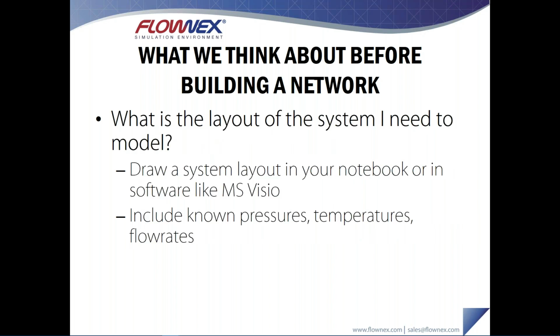The next thing that we need is some layout of the system. Often what will happen is engineers will be working in big plants, or somebody will describe a new system on a whiteboard, and we'll start building right away without actually considering the system in more detail. Taking 10 minutes or so and drawing out the system, be it in a notebook or even in something like Visio, you can gain a lot of insight into the system, make sure that you understand the layout of all the components, and more importantly, include information you already know about the system. Known pressures, known temperatures, known flow rates, elevations inside of the system. Any information that's going to be critical at the simulation stage.